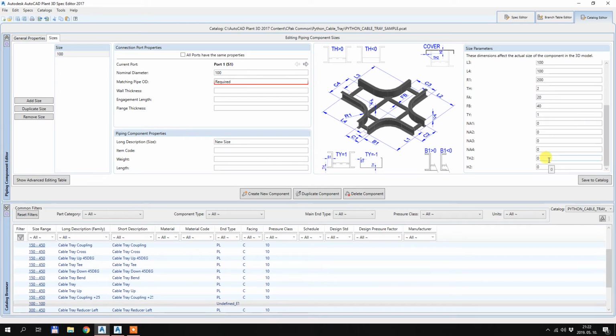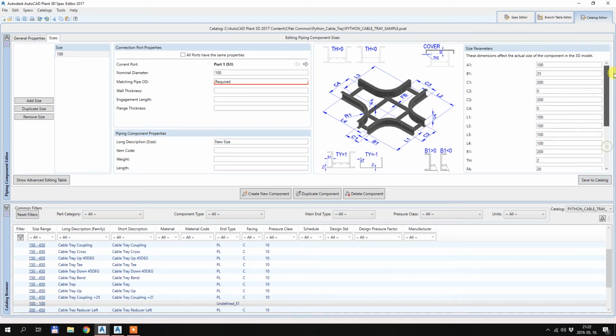You know, because here in the spec editor you are not seeing if you are entering some strange values which is generating a geometrical error. So I try to limit the human error as much as possible. But for example, if you enter a negative A value, I think you will have an error for sure. So this is it in the spec editor.